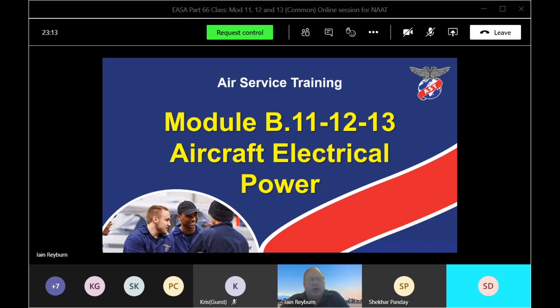So we'll be wanting to keep the input to the primary coil of the TRU constant. So my output will be constant, and that output will be 28 volts. So as you can see down here, gents, here's my input. It doesn't matter what the supply is, but 240 out. There's the primary turns. There's the secondary turns. And again, it's a lower value. You can see there, I've got more turns to less turns in the secondary. So it has to be a step down AC transformer. So that's the transformer part of the TRU.